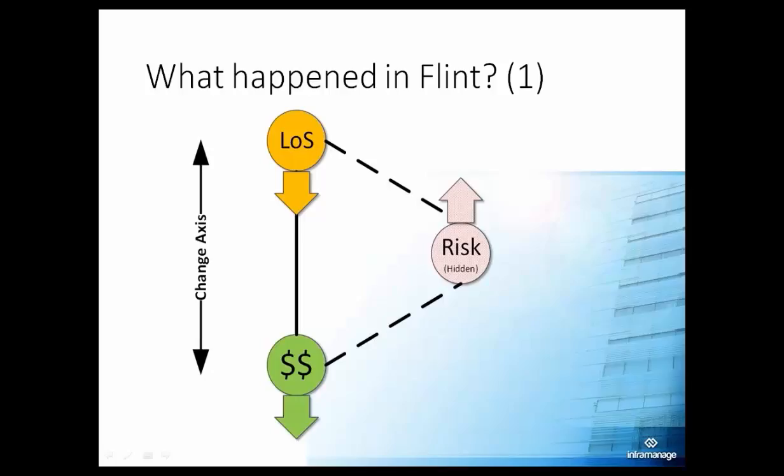There you go. So I would suggest that if you have a chance to try out some of the technologies for, say, vibration analysis, there's some temperature analyses, there's all kinds of things, and I do not have any recommendations on one company over another, but if you have a chance to try it, perform your own special study to see, if I get this information, what does that tell me about my pump? How could I change my maintenance regime knowing this? And then look at what you did before, look at what you do now, and see if it actually saved you the amount of money it cost you to do the analysis. So the bottom line is you want to save it.